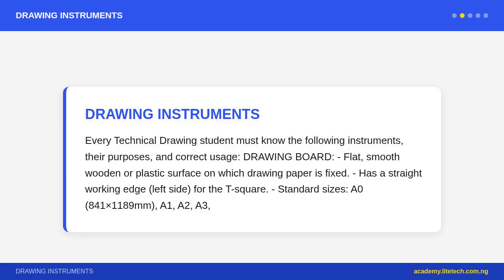Compass, pair of compasses. Used to draw circles and arcs, and to transfer measurements. Has two legs, one with a sharp steel point, pivot, one with a pencil or pen. Large compass for circles, small bar compass for small circles and accurate work. Never force the pivot, it must sit precisely on the center point.